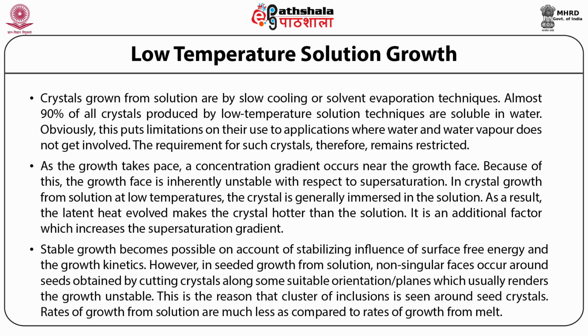Stable growth becomes possible on account of the stabilizing influence of surface free energy and the growth kinetics. It is possible for this reason that stable growth phases are always singular in solution growth. However, in seeded growth from solution, non-singular phases occur around seeds obtained by cutting crystals along some suitable orientation or planes, which usually renders the growth unstable. This is the reason that clusters of inclusions are seen around seed crystals.